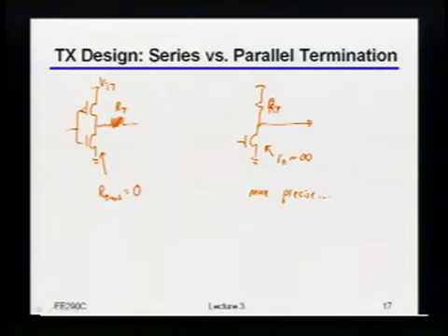It's not that getting output impedance is free, but remember, increasing output impedance, at least fundamentally, doesn't have to cost you power, right? Getting really low output impedance pretty much always means somehow you paid for it, because something somewhere needed to sustain a lot of current with a very small voltage. So in the example of, let's say, like you were complaining, you have really crappy technology with GMRO of only 3 or something like that, and that just wasn't good enough. Well, what do you do? Cascode. Yeah, you cascode, or you make a slightly longer channel, or one of these other kinds of things, right?